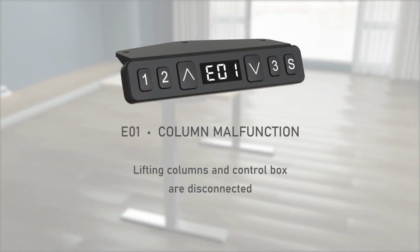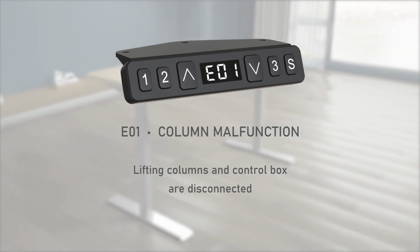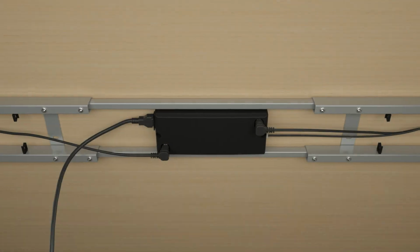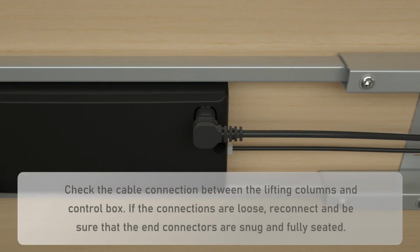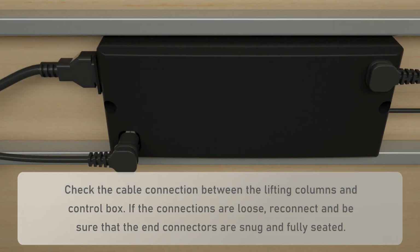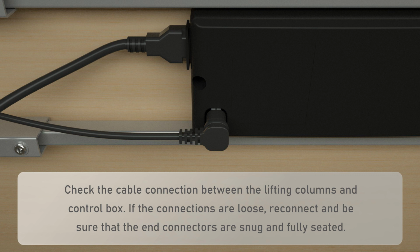E01, column malfunction. Lifting columns and control box are disconnected. Check the cable connection between the lifting columns and control box. If the connections are loose, reconnect and be sure that the end connectors are snug and fully seated.